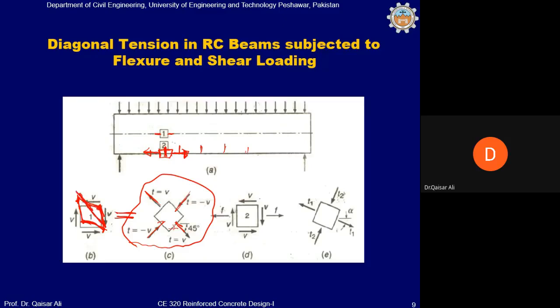And whenever there is elongation of length, you know that there are some tensile stresses acting on the element, because without the tensile stresses, elongation is not possible. And there is shortening along this, so this means that there is a compression. So this case is just equal to this case. You can see now the two cases, they are exactly equal.